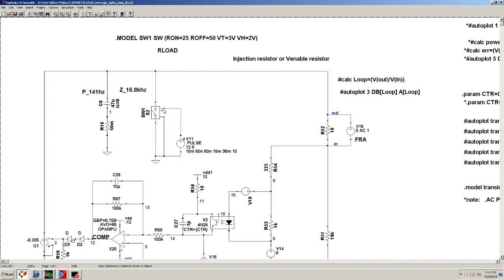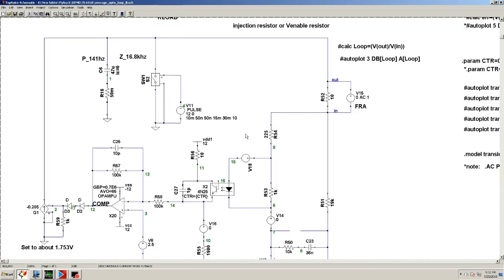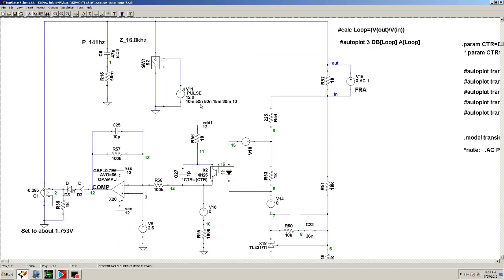Basically, when this voltage turns it on, it's going to be 25 ohms, and if you have 25 ohms, you're going to have half an amp. Then when it turns off, it should be the equivalent of 50 ohms. So when you're switching on and off, it's going to go from half an amp, quarter amp, half an amp, quarter amp. Okay, so I have it set up, and I go.